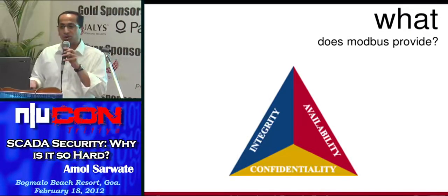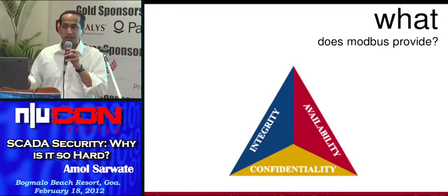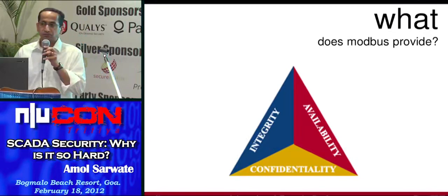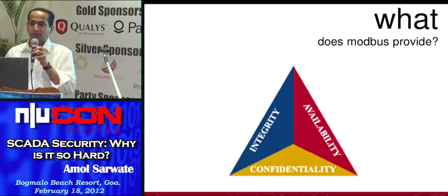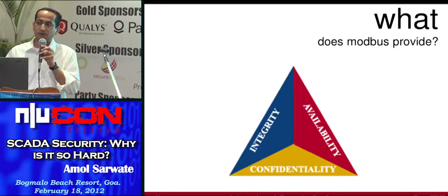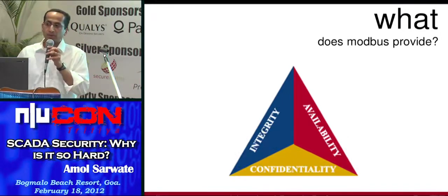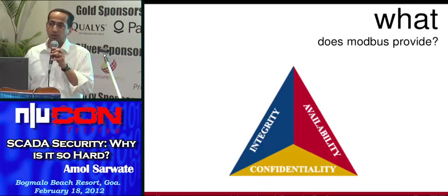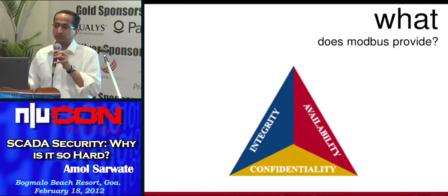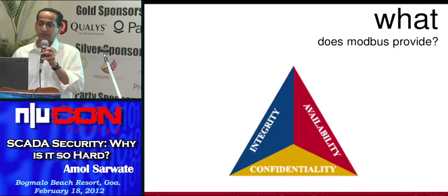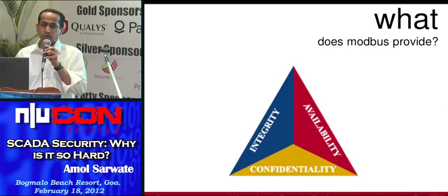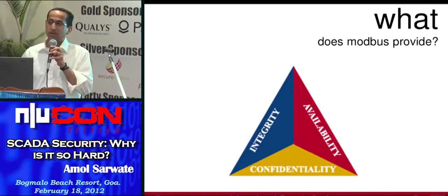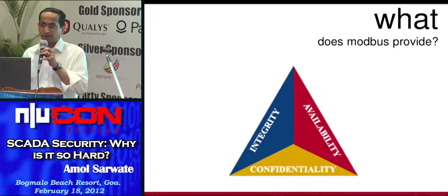There is also no integrity here. Any type of man-in-the-middle attacks are possible because it's a pretty simple plain text protocol. You can just change data on the wire in the middle, and those types of attacks are possible. But Modbus is the most famous, the most widely used protocol in the industry right now for talking between PLCs. It's used in industrial control systems, in automobile manufacturing plants, and so on and so forth.